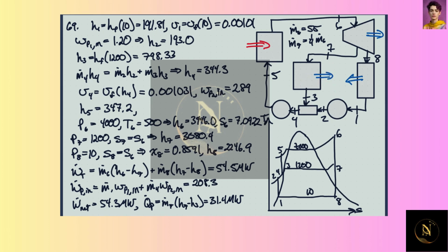So we can figure out kind of the normal process here. Enthalpy coming into the pump, specific volume coming into the pump, work by the pump, from this stuff and the change in pressure. And then the enthalpy coming out of the pump, again, is this plus this. And now into the mixing chamber,